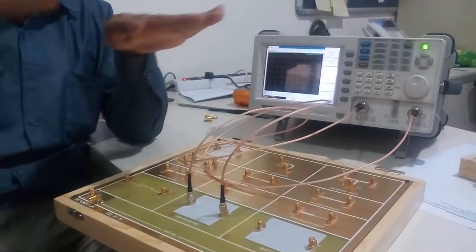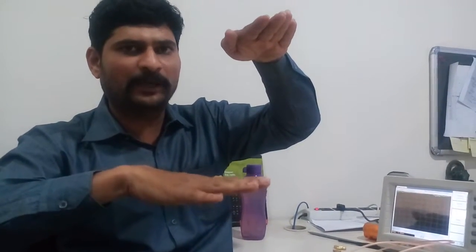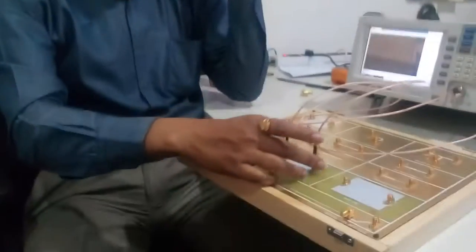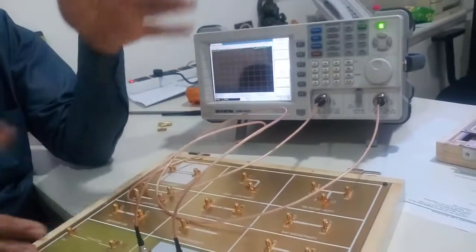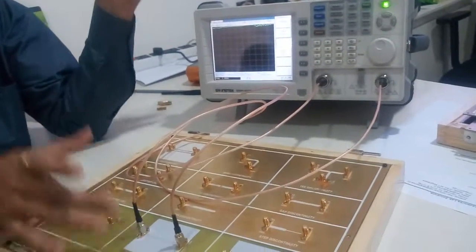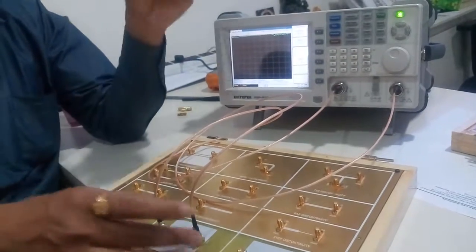Here the loss is not optimized because only the upper side ground plane is there, the microstrip, the active part is there, and on the lower side nothing is there. When the field comes to the lower side of the dielectric, the FR4, it can't find any metallic surface over there, so somewhat the loss is going to be increased. So here all the CPW lines are propagating in the dominant mode. In the dominant mode we can compare that a little bit of noise loss is added over here. So thank you.